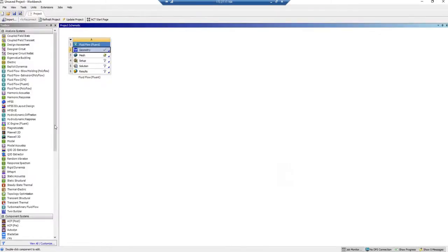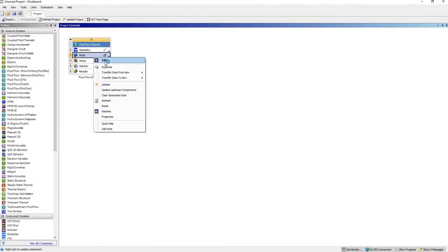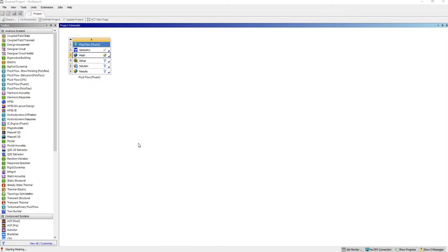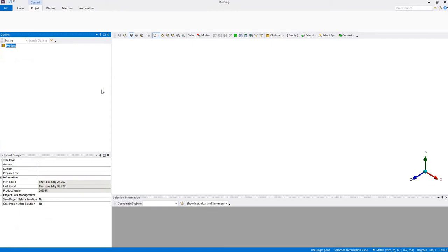Close this one. Let's do the mesh. About the mesh, this is one of the most important things in this kind of simulation, because a lot of them fail because of the mesh. You'll see, when you start the simulation, it keeps diverging. It keeps diverging, and continuity will go off. So why is it happening? One of the reasons is the mesh. The other reasons I'll explain as I go through setting up the simulation. One core reason is your mesh.